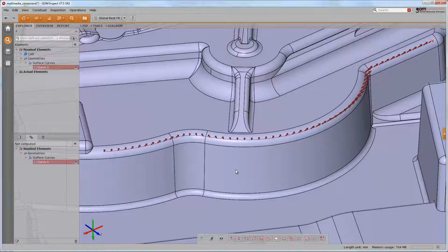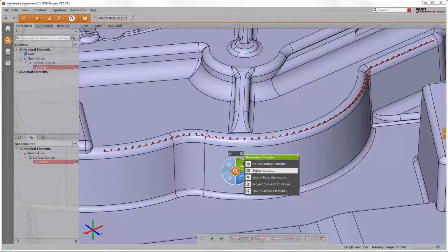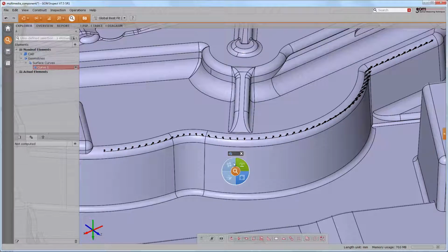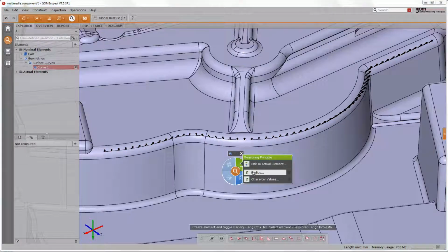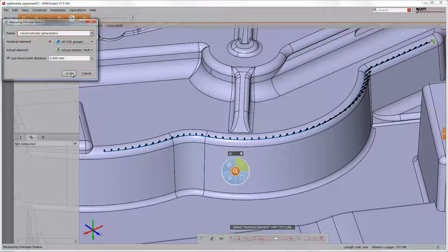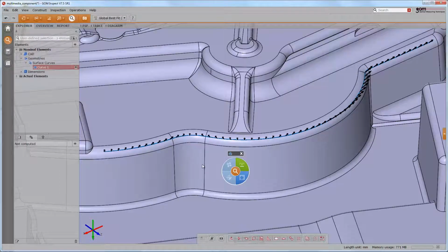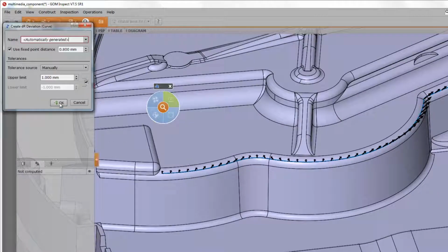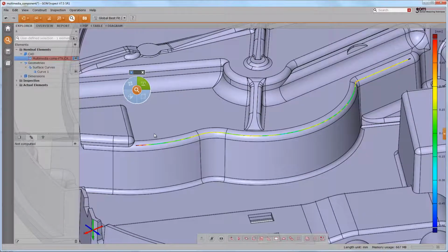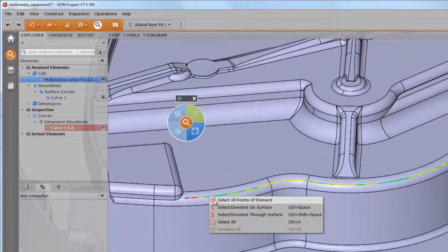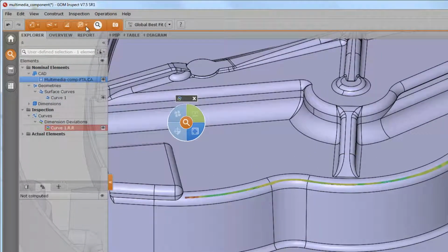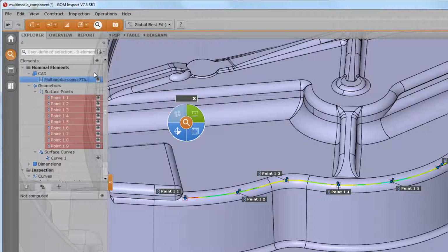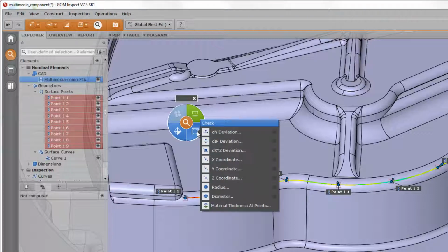We can reproduce the same on the actual data via measuring principle fitting curve. To determine also the radii, choose the measuring principle radius. As everything is being calculated, we choose the check deviation radius. Discrete values for the radii deviation are available over the button Point-Wise Inspection in the main toolbar. So perhaps we would like to use equidistant inspection points for the radii.